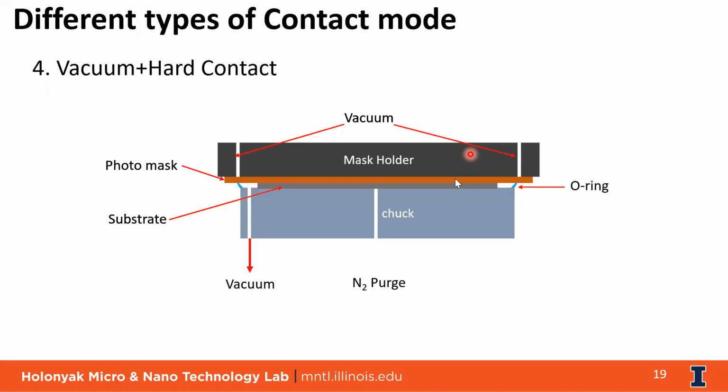So that's the reason you have to do a sufficient soft bake, not too low or too high. When you bake it too little, you'll be leaving too much solvent, which can increase your development rate. But if you bake it for too long, your photoresist will be really dried out and it will change your development rate very much. So it's a trade-off how much you do it.